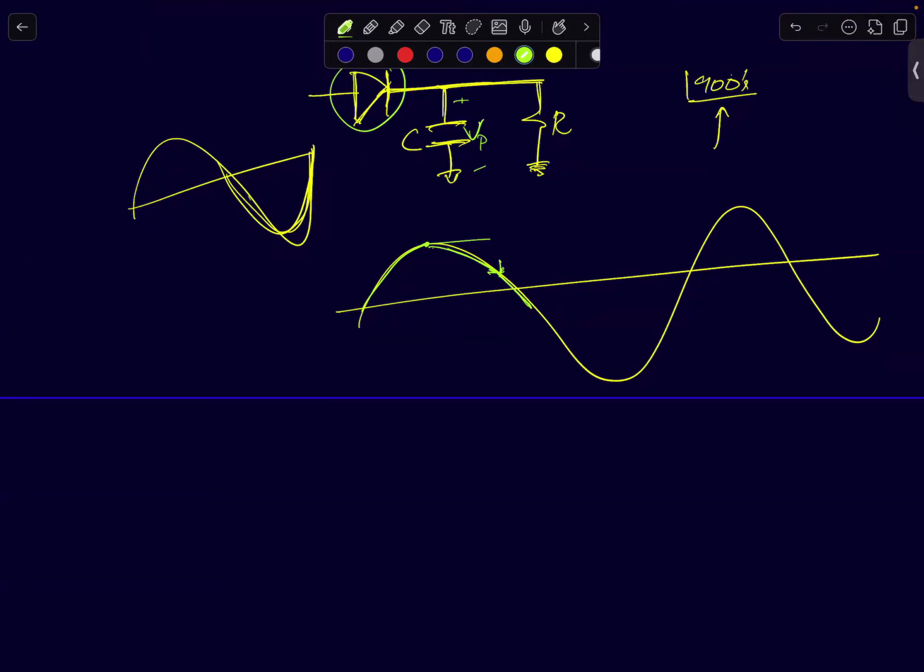It's an analog circuit, so I just need a DC voltage to operate. I just need to extract the DC out. I don't really care if the waveform is shifted a little bit, as long as I get that VP volt stored across the capacitor. I have stored its peak. So it's called peak detector. The terminology may be confusing, but remember it was introduced in the early 1900s, when digital didn't even exist.